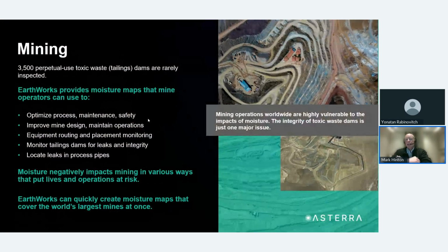So tailing dams can be particularly challenging assets to monitor. Many around the world lack clear ownership. Some of the older ones lack clear ownership, and that can hamper inspection regimes and so on. But often, even those which are orphan assets, if you like, the local municipalities still have a responsibility and require some form of risk assessment as part of their responsibilities to their local population and the local environment.